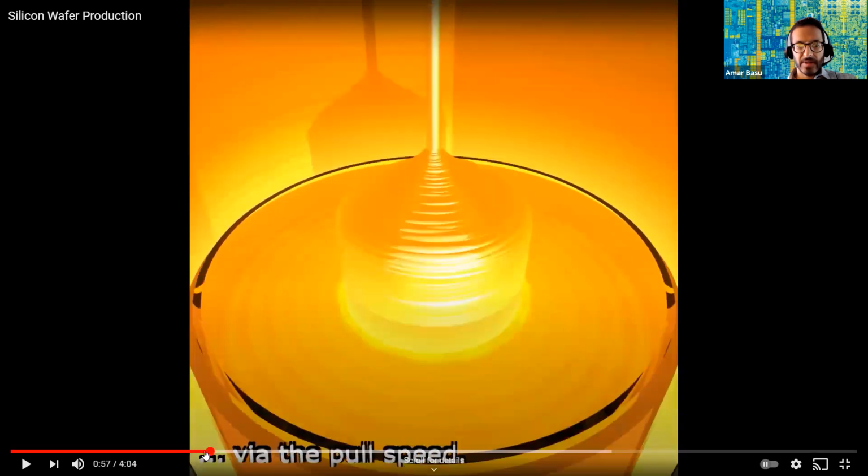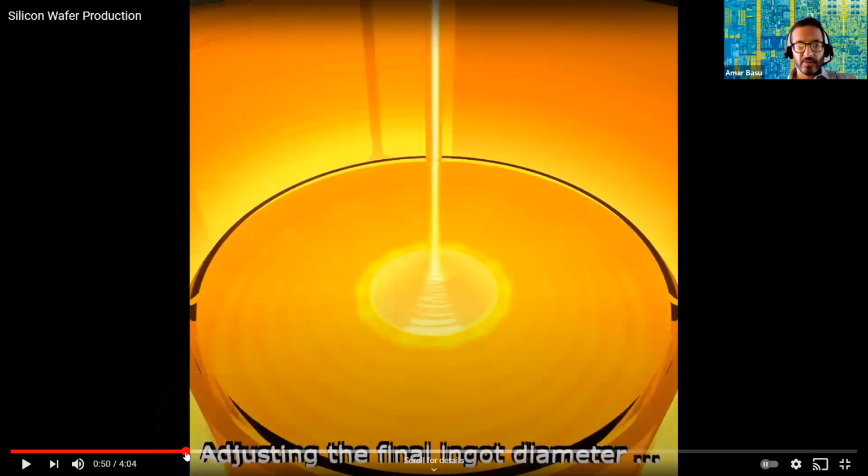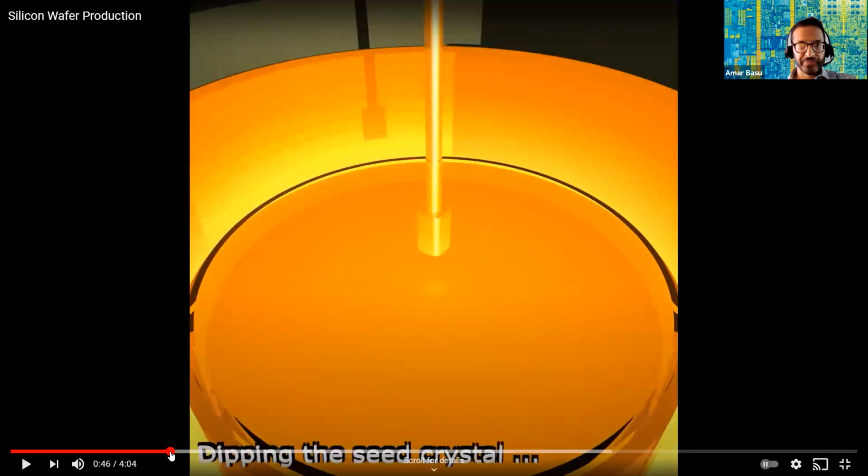If you look at what's happening on the atomic scale, the seed crystal is single crystal silicon, and you can imagine the atoms in the melt attaching themselves onto the end of the lattice. Because of the high temperature, the atoms organize themselves into a single crystal form.